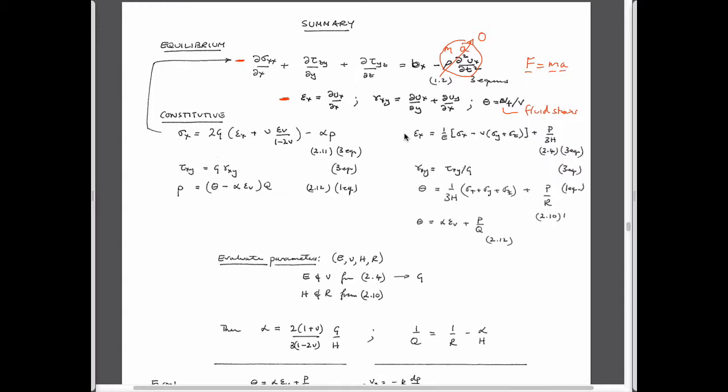We defined our constitutive relationships in terms of what you might call the forward relationships, which relate strains to stresses, but now also to fluid pressures. This is effective stress. You can also write these back the other way. You remember when we talked about solving two-dimensional or one-dimensional problems, we had to constrain them in some way by doing plane strain or plane stress, etc. So we manipulated them to satisfy that condition, but we also switched them over to define not strains as a function of stresses, but stresses as a function of strains.